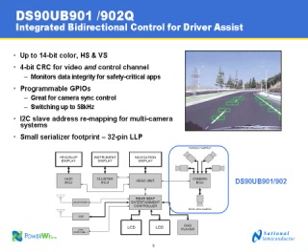Programmable GPIOs are available, and this again just allows the camera and the host controller to talk to one another. Synchronization signals can be sent from the host to the multiple cameras to make sure all the data is coming in at the same time and synchronized. And these GPIOs can switch, as we note here, at about 58 kilohertz maximum frequency. So that allows a lot of flexibility with transmitting this data. And both of those are particularly unique to the 901, 902. Yes, they are.